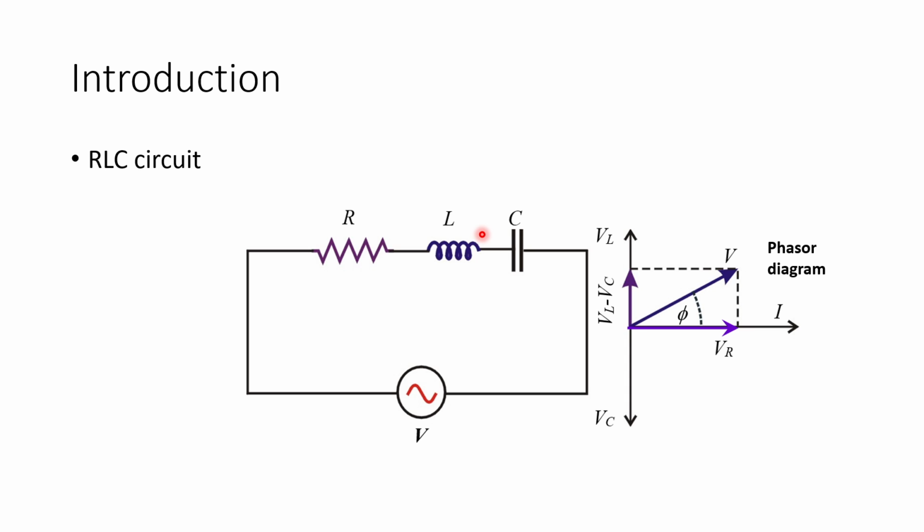However, for the inductor, there's going to be some magnetic flux going on here, and for the capacitor, there's going to be charging and discharging phenomenon going on. Therefore, this causes the phase lag between the voltage and the current, and it gives what you call the reactance, which is equivalent of the resistance, but it does not take away any energy. For the inducting coil, the reactance is XL = 2 pi f multiplied by L, where L is the inductance of the inductor, and for the capacitor you would have the XC, the reactance of the capacitor, which is 1 divided by 2 pi f times C.